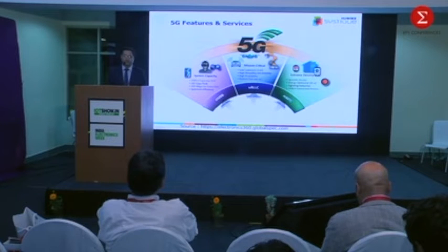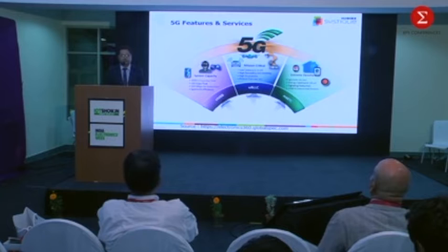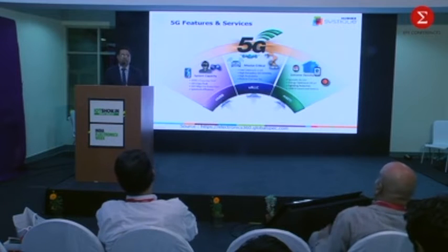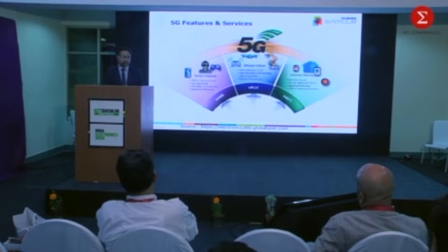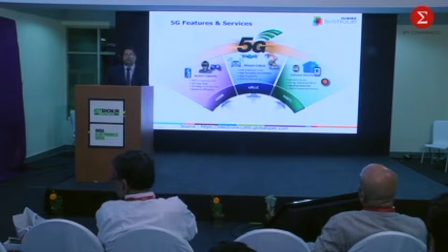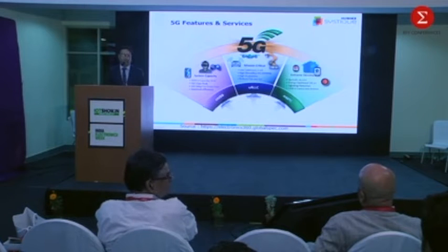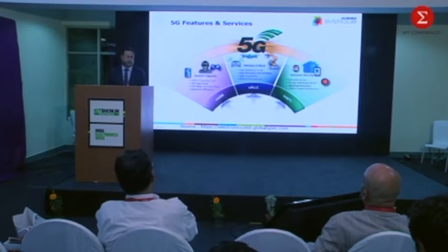The first is eMBB, or enhanced mobile broadband, which targets high data throughput of the order of more than 10 Gbps, high system capacity of the order of more than 1,000 times that of LTE, and a much better spectral efficiency than LTE, 3 or 4 times that of LTE. So its use cases are high-speed mobile broadband, virtual reality, augmented reality, gaming, etc.